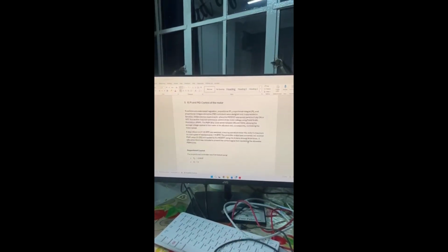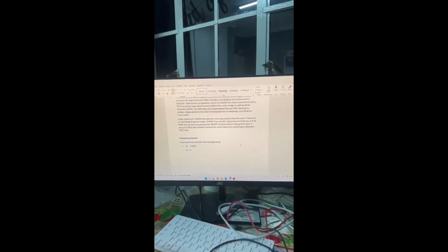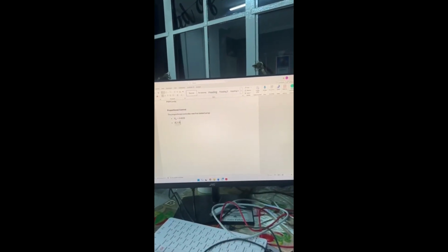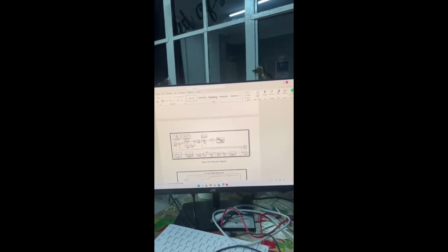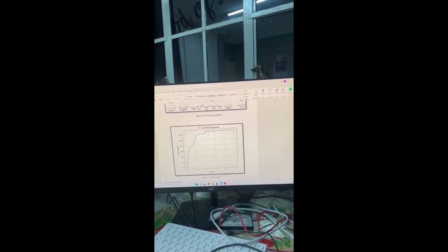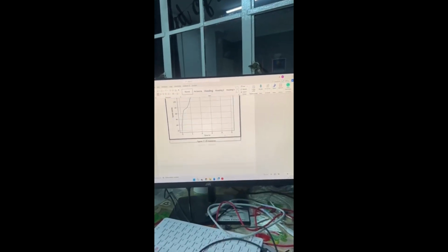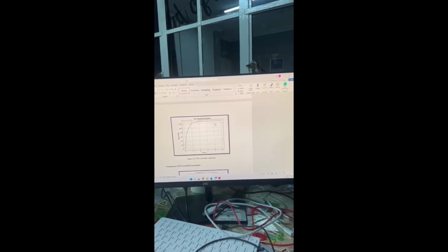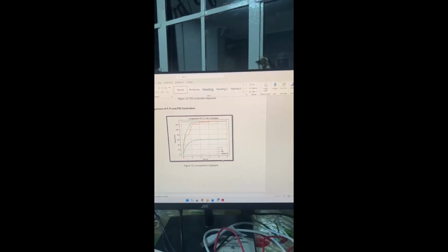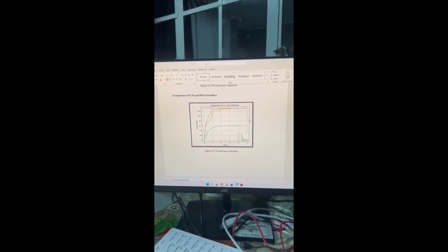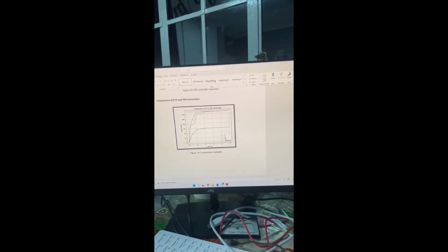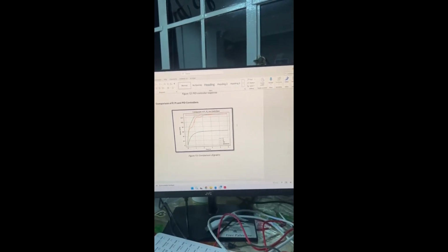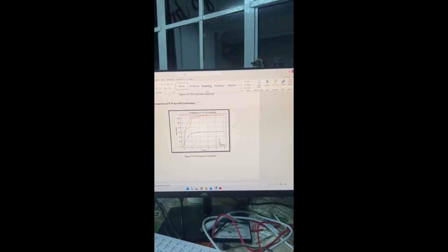Lastly, I integrated PI and PID control for the motors. I chose certain KP and KI values, which I deemed appropriate. And then I constructed my P response graph, my PI simulating diagram. I generated my PI controller response and my PID as well. And lastly, I graphed them all on one graph to compare and see what improvement can be made, which parts can be taken from which graph, and how I can overall fine-tune my system.